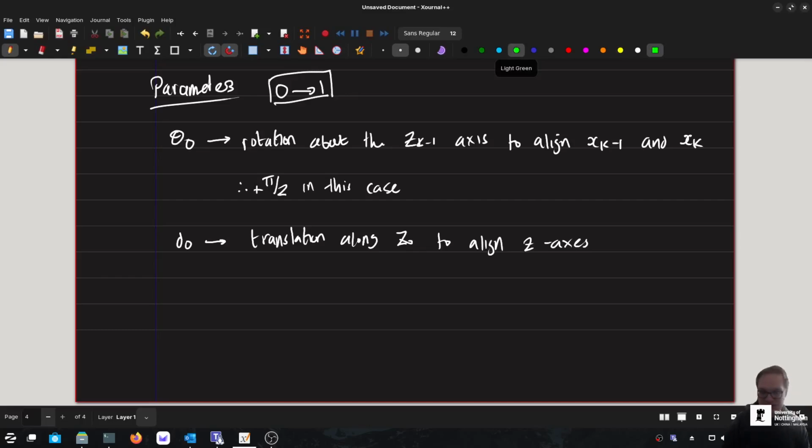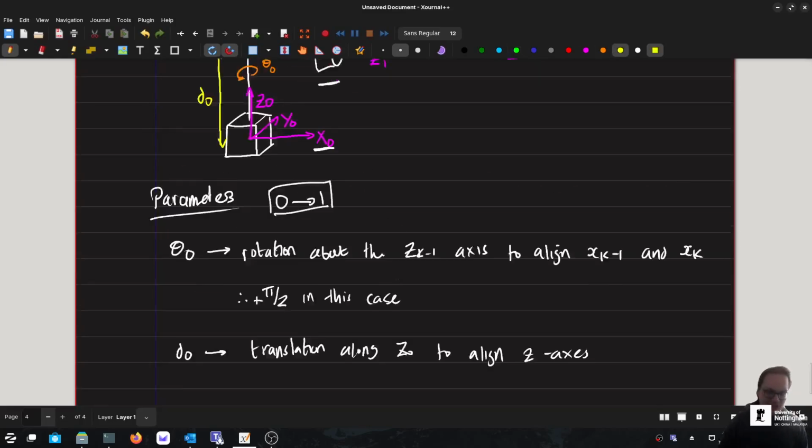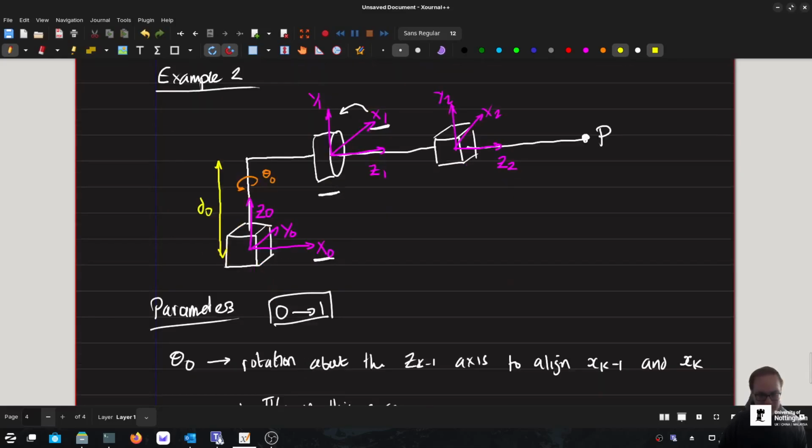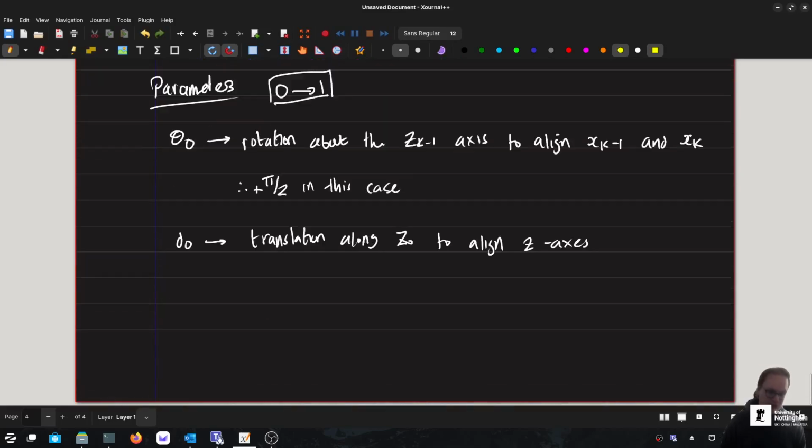And it's obviously because it's a prismatic joint, and we assume also the prismatic joint will only change in the z direction. It's not going to be prismatic, we hope anyway, in the r. You need to have another joint here, but no, it should be only in the z direction it's prismatic. So we will say that d0 is the variable. We haven't got that value.